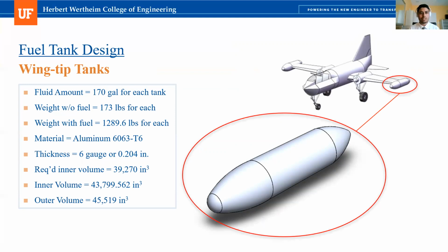So we decided to integrate wingtip tanks into our BC-1 aircraft, because we wanted to take advantage of the fuel weight. What I mean is when the wingtip tanks are on the tip of the wings, along with the weight of the fuel, this would reduce the tendency of the wings to flutter around.